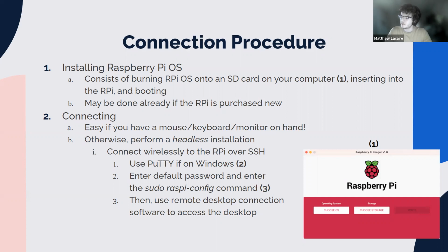To go over it quickly, what you would do is take out the SD card and put it back into your Windows computer. I'm sure there's a similar process for Mac. You can add certain files within the actual OS information that put both your wireless username and password in, meaning that when you put the SD card back into the Raspberry Pi, it now has the information to connect to your Wi-Fi. It will actively be listening for connections over your IP. There are a few different ways of doing this, and I know I have these numbers here for a reason.